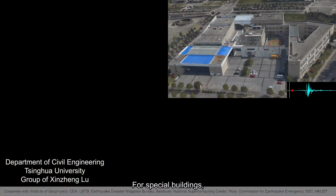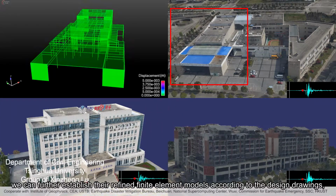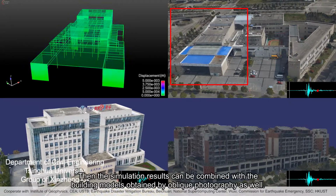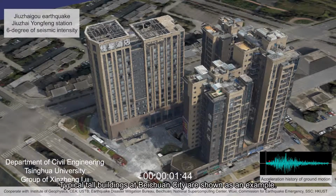For special buildings, we can further establish their refined finite element models according to the design drawings, so that the seismic responses of every component of the buildings can be obtained. Then the simulation results can be combined with the building models obtained by oblique photography as well. Typical tall buildings at Beichuan City are shown as an example.